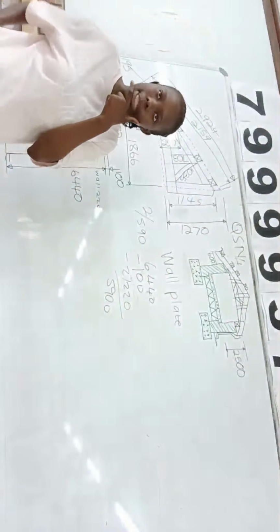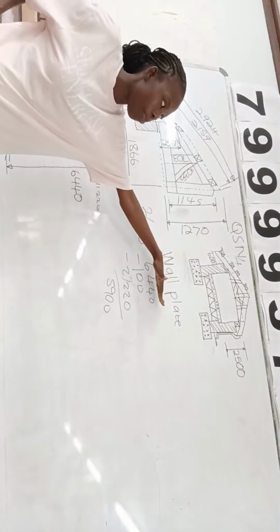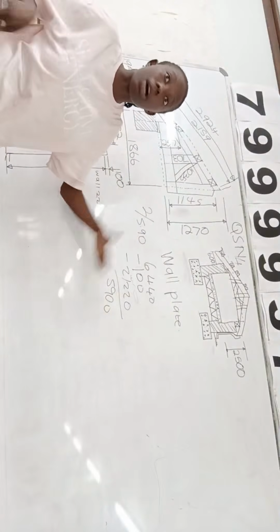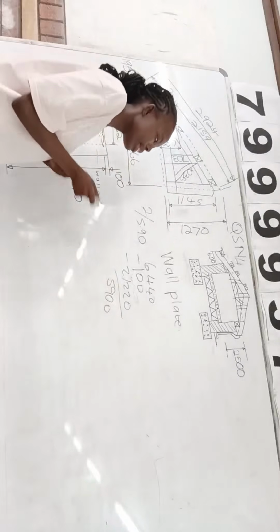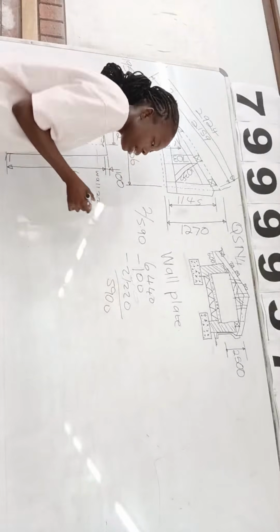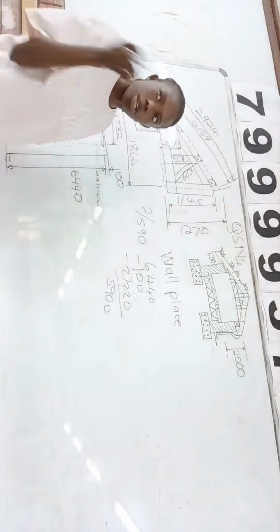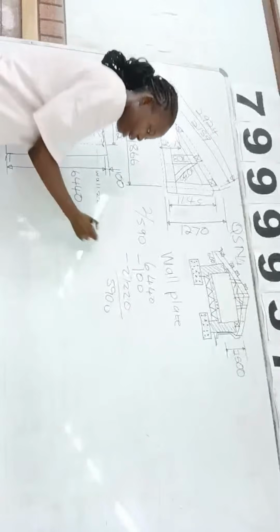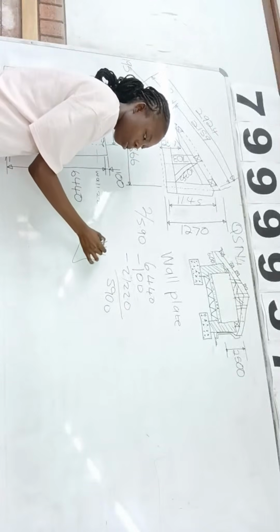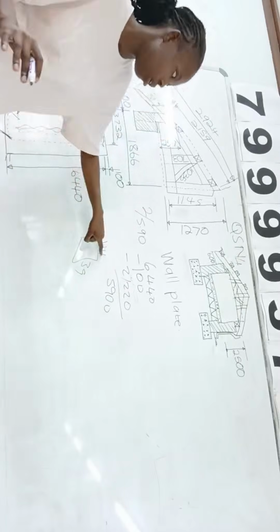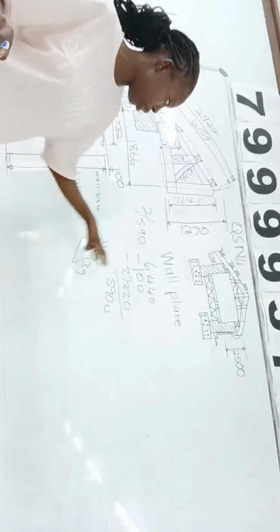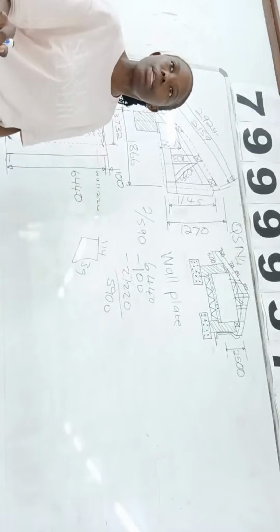So it's 5,90. And then what I want to know from you is that wall plate and the treatment to the wall plate, they're going to be separated. What I want to know from you is, are we going to calculate the perimeter on the wall plate or on the treatment of the wall plate? Again, this is a wall plate. They said our wall plate is 114 by 39. When I say perimeter, I mean all the sides. Again, there's that formula that says 2 of 114 plus 2 of 39. So do we do this on the wall plate or on the treatment?